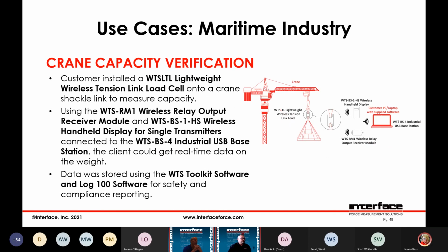This one is a crane lifting application. We use our WTS LTL, so this is a lightweight wireless tension load link. It's transmitting its signal from the weight that it's lifting to a wireless handheld display, also to a relay module, and to the PC.